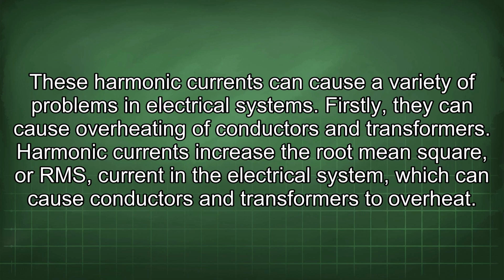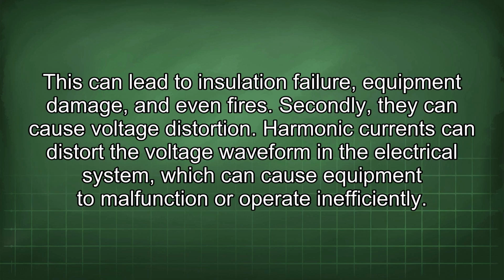These harmonic currents can cause a variety of problems in electrical systems. Firstly, they can cause overheating of conductors and transformers. Harmonic currents increase the root mean square, or RMS, current in the electrical system, which can cause conductors and transformers to overheat. This can lead to insulation failure, equipment damage, and even fires.